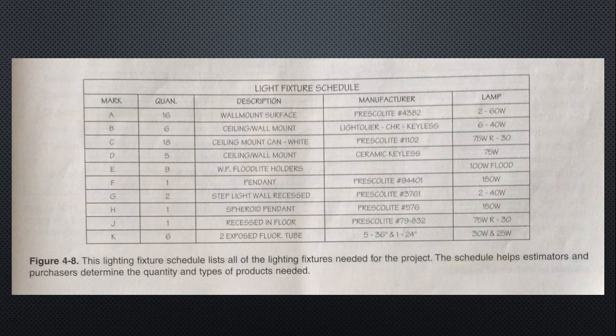Electrical schedules. Electrical schedules are tables that list items such as fixtures, power requirements, panel board information, receptacles, transformers, and motors. Schedules save print reading time by placing information in one easy to find location. This helps with project estimating, purchasing, and construction. The following are some examples of schedules.